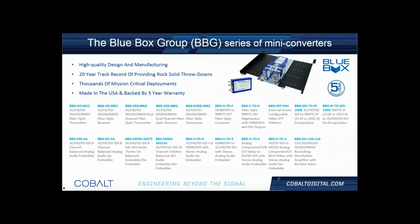different categories again. Similar to the Open Gear platform, we have different categories if you want to do a fiber TX in a single channel or dual channel, and we can also do a bidirectional, if that's what's desired. We also have an HDMI to fiber, fiber to HDMI, and as an example, an SFP capable blue box that allows you to have a transceiver. It can be a TX, RX that converts to SDI or HDMI.